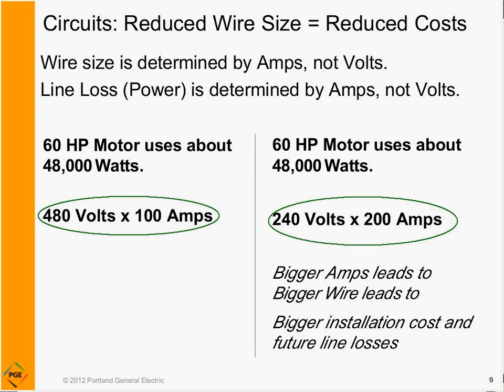The other question that can come in is, oh, I'm out of capacity in my panel where all your circuit breakers are, and you have to change the panel. I've had some very bright managers come to me and tell me that if their equipment is at the end of life and can go to higher voltage, lower amps, in this case, they save 100 amps in the panel by swapping out a 240 volt unit for 480. So energy efficiency projects can have other benefits other than just the electric bill.